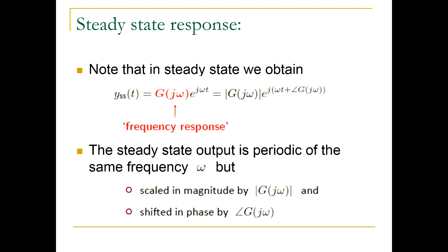So if I apply a periodic force to this and shake it with a certain frequency and force of the same amplitude, then if it's a light thing, the amplitude would be larger if the frequency of the input is low. So if the frequency is low, the amplitude of oscillation, which is the output, would be high. If I try to shake it very fast with a different frequency but the same input amplitude, the amplitude of oscillation of the output would be smaller.